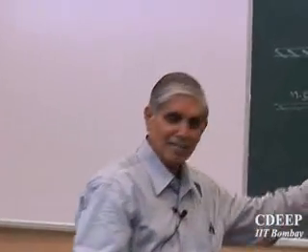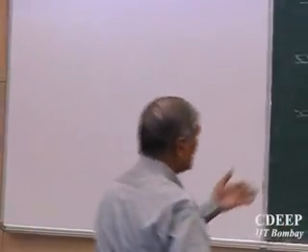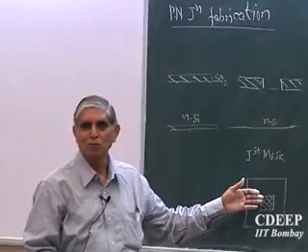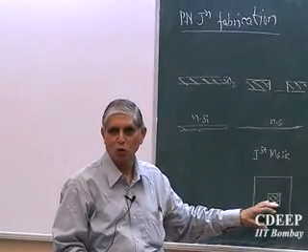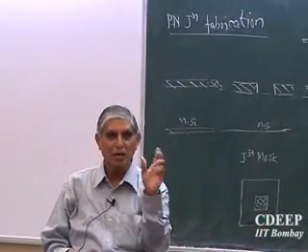What should PPR be then? It's already linked. When I shine light, it breaks. So when I shine light, that area is etchable. Otherwise, it is unetchable. What should the mask kind be then? This was a clear field mask, so if I am using PPR, it should be a dark field mask with an open window, because only there can it be etched.